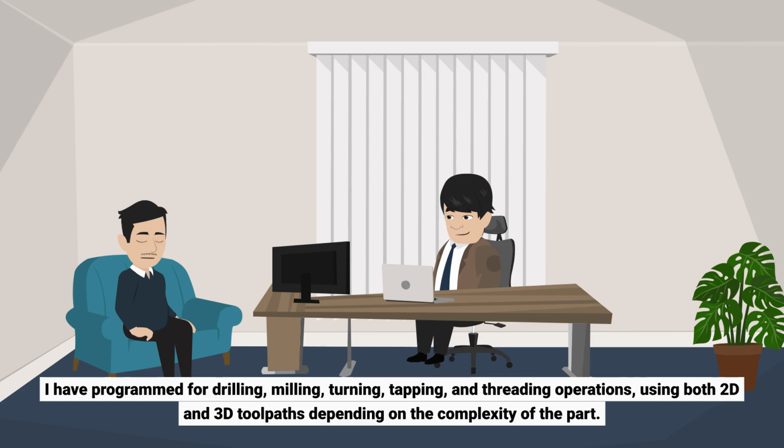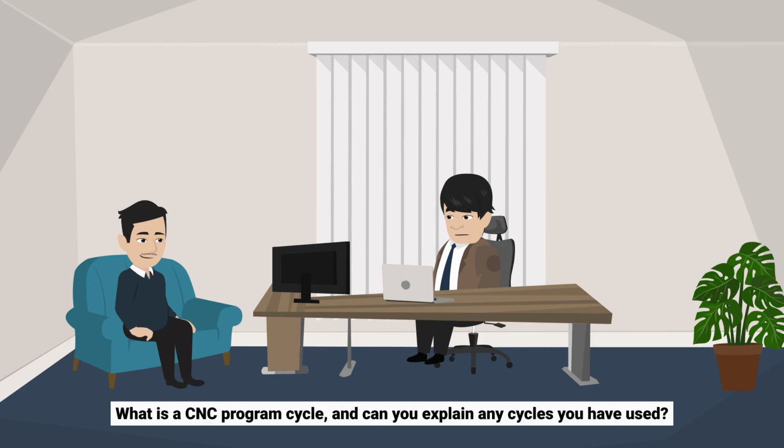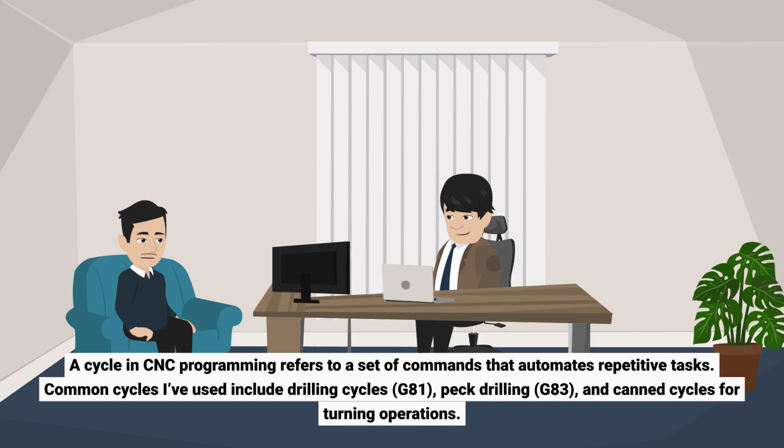I have programmed for drilling, milling, turning, tapping, and threading operations, using both 2D and 3D toolpaths depending on the complexity of the part. What is a CNC program cycle, and can you explain any cycles you have used? A cycle in CNC programming refers to a set of commands that automates repetitive tasks. Common cycles I've used include drilling cycles G81, peck drilling G83, and canned cycles for turning operations.